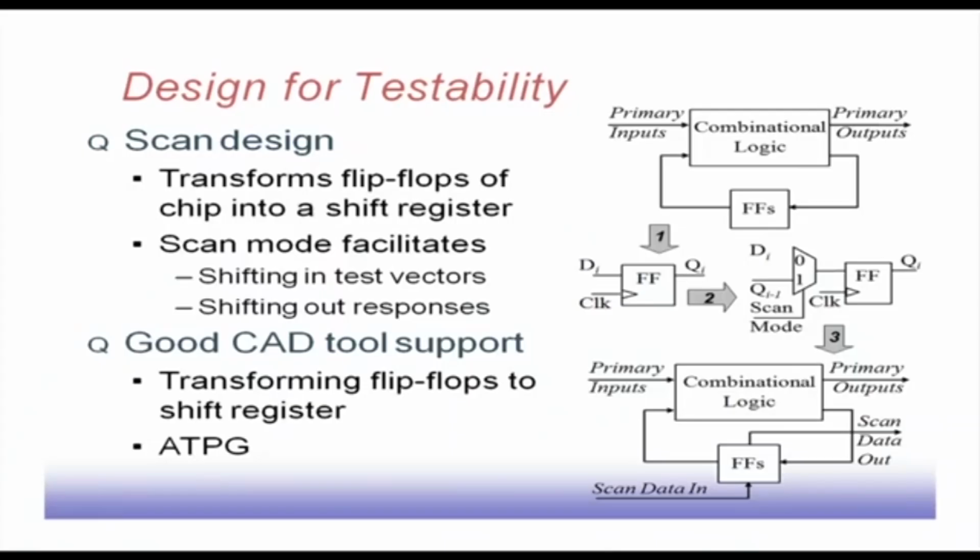Where we have flip flops, test pattern generation is a complex problem, but once we have this scan incorporated into the system, this entire system can be treated as a combinational circuit only. So, that way the combinational ATPGs can be used for generating the test patterns.